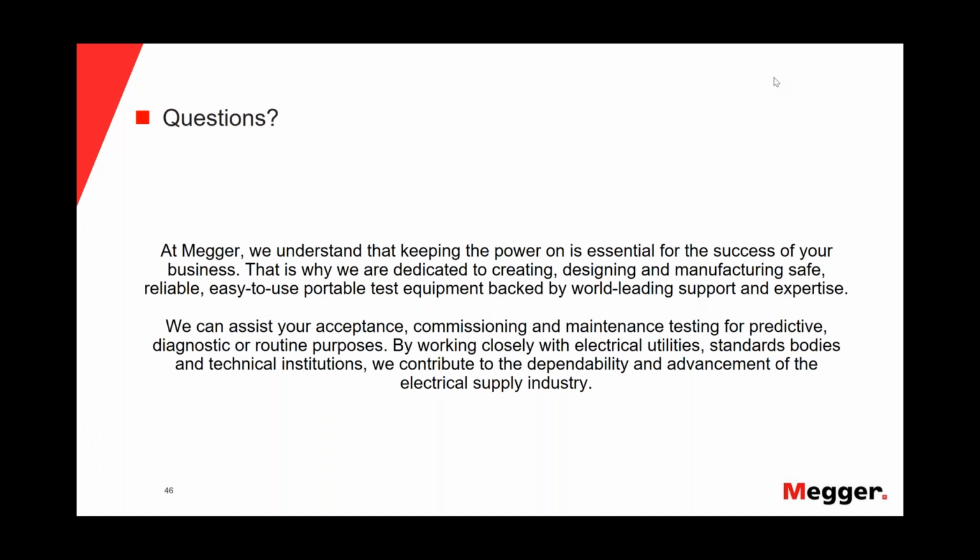Well, if I understand the question correctly, there is no waiting period. Once you bring the cable up to the particular voltage level you want to use to evaluate the cable for PD, the PD doesn't have a waiting time to start showing up.